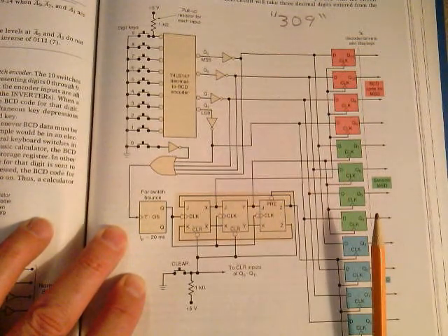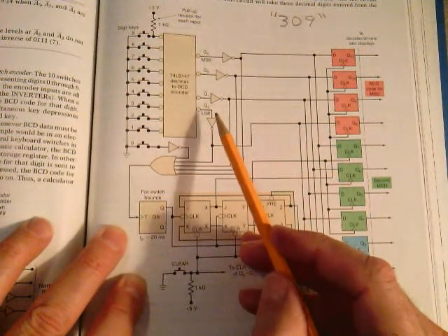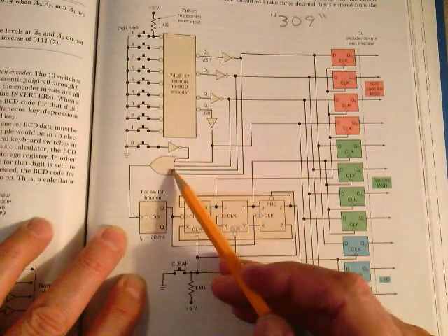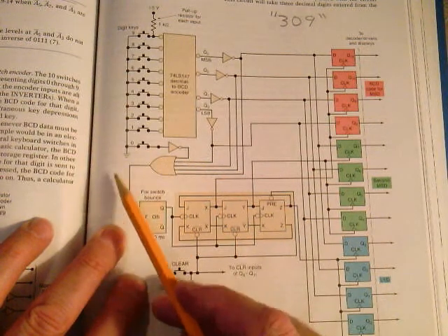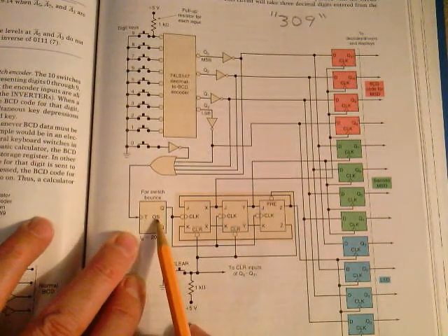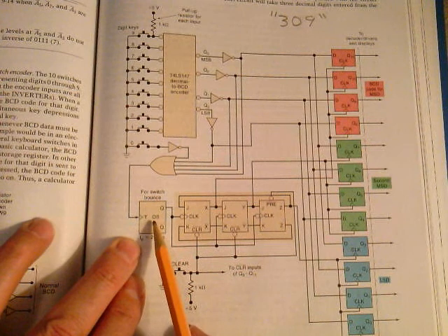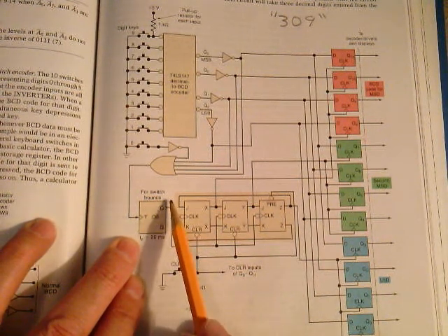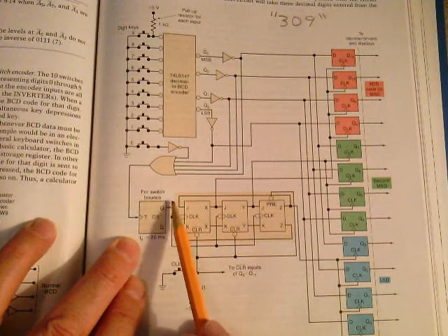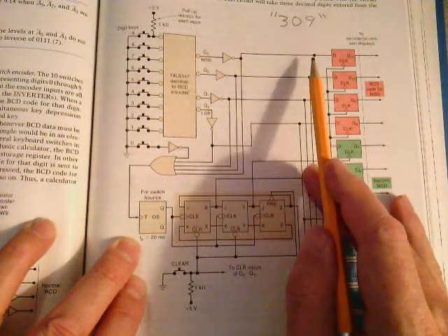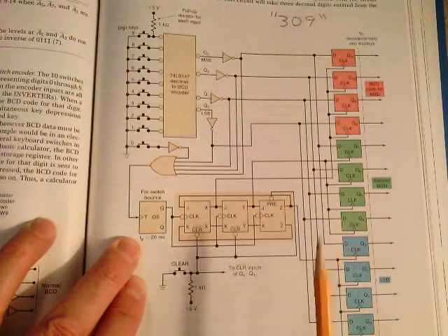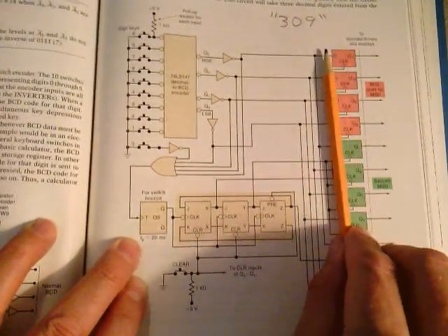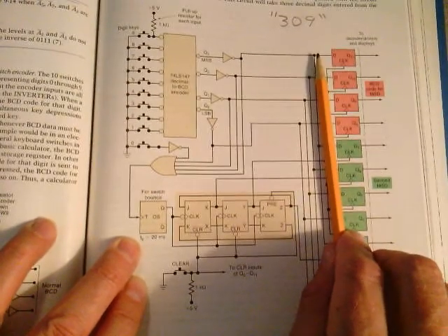Let's see what happens. At the same time, when this goes to a 1 here, that 1 goes through this OR gate, and that 1 produces a 1 here, which is a clock, which fires this one shot. So the output goes high, and it's high for 20 milliseconds. That 20 milliseconds is more than enough time for all this 3, 3, 3 to get set up. Remember the setup time? You have to allow time for this to get set up and stabilize on the input here.